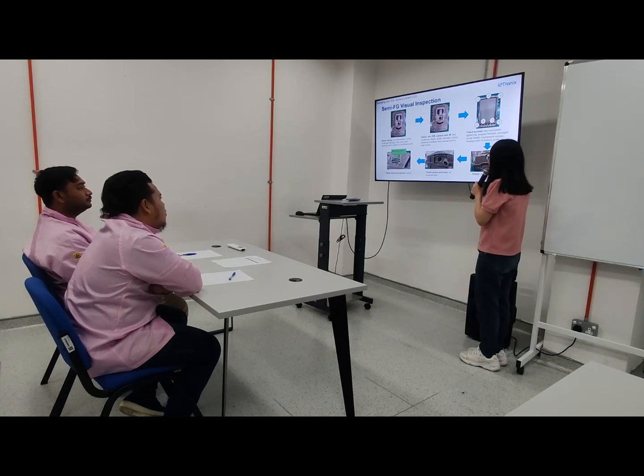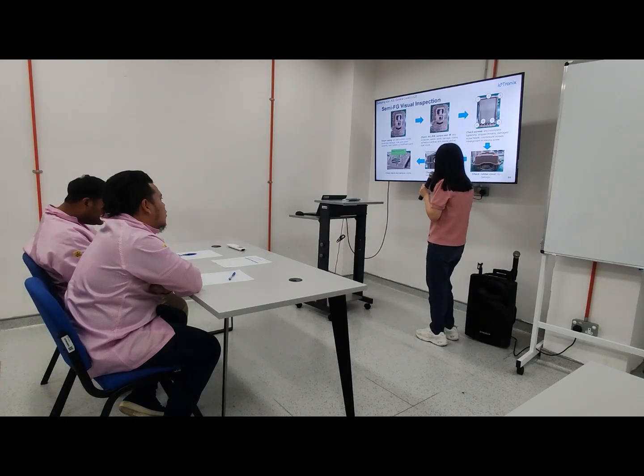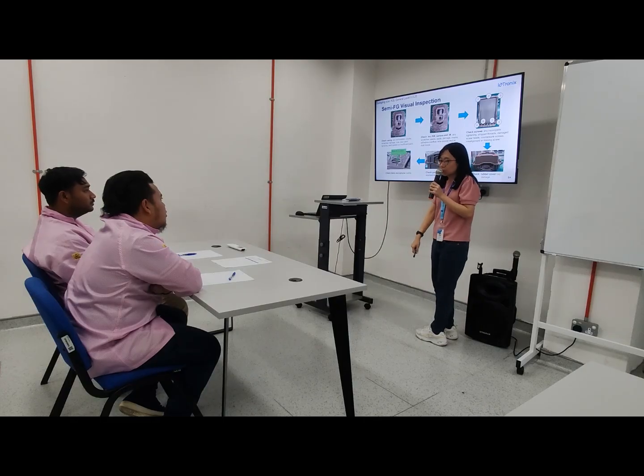Okay. After the screws, next we go on to rubber cover checking. Make sure this is okay, no damage. Next we will check the power port area. The most common defect here is that we can see the wire, which means the assembly process is not okay. Then they have the exposed wire there.